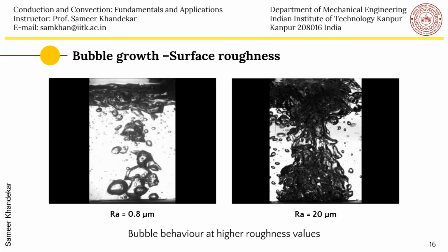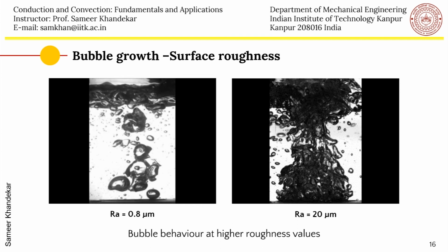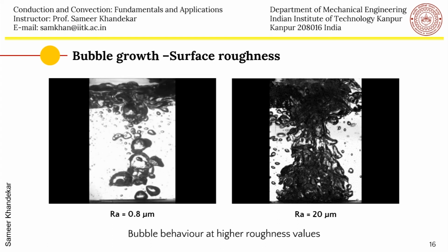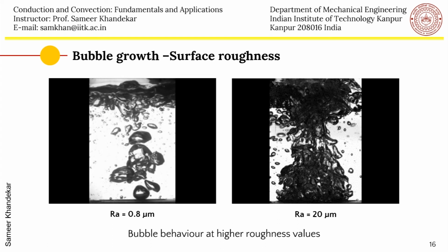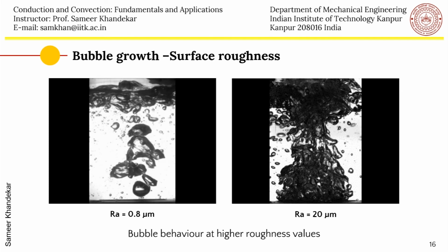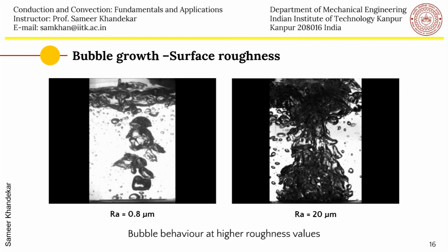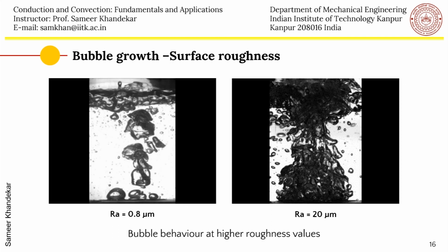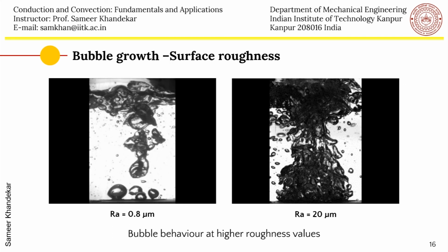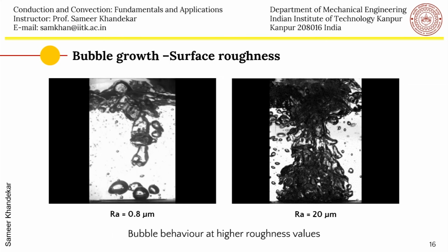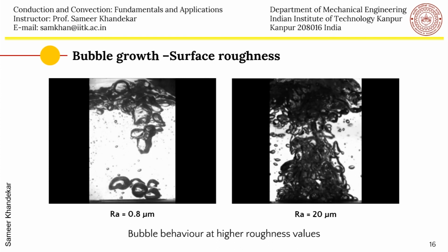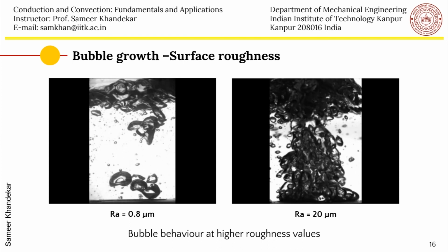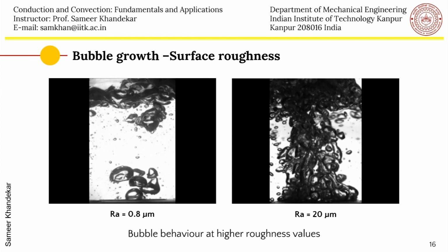In fact, now it is very difficult to make out individual bubbles. The nucleation sites are quite large in number because of the higher roughness of the surface, and you can see now fully developed nucleate pool boiling taking place on these surfaces.